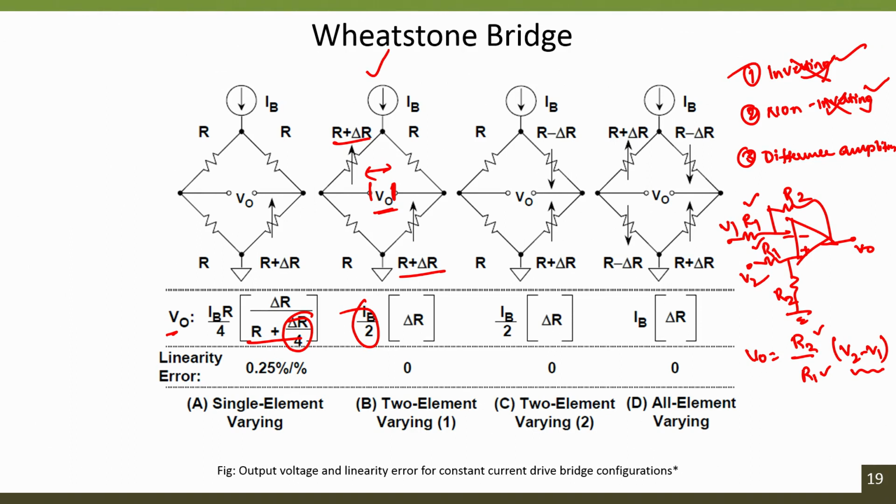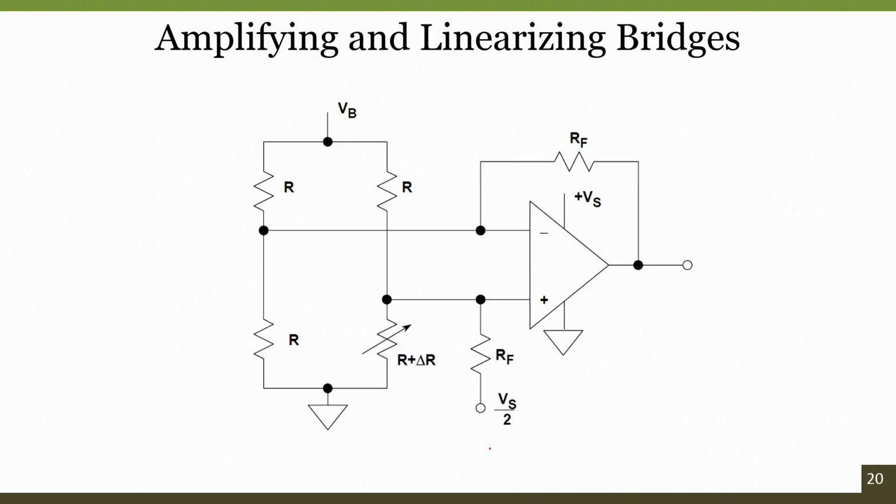Of course, there are other ways of doing it which can avoid the effect due to input resistance, that is the instrumentation amplifier, the 3 op amp based instrumentation amplifier. Even though it uses a differential amplifier inside, because of the topology or configuration of the 3 operational amplifiers, the input impedance is very high. At the same time, the CMRR, the common mode rejection ratio, the ability of the system to reject the common signals, is also high. So, this is a difference amplifier.